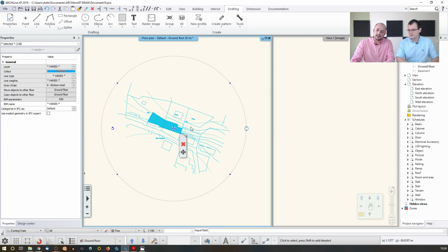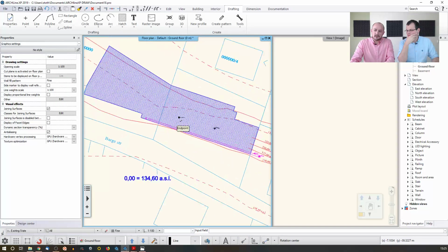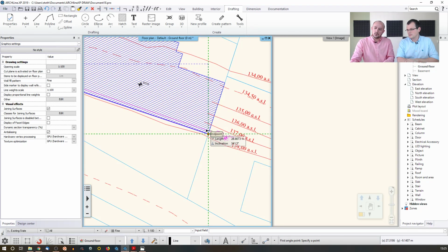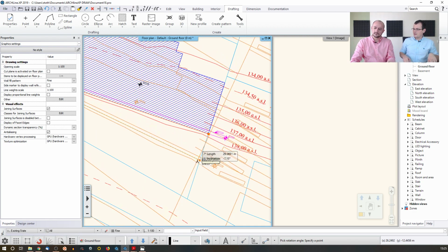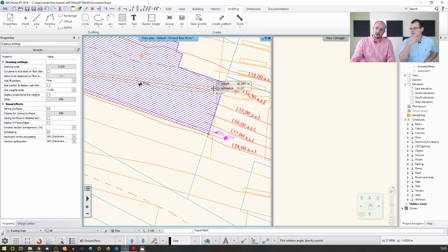So I click here, instead of the classic graphical rotation. So I have the rotation options, and now I can find the rotate from. This is a very handy tool because this allows you to set up a rotation origin. This is where I would like to rotate this whole content around. And then I can click and pick up a point, so one point, the rotation origin, stays where it is, it's pinned down, and the other one moves around it. Yeah, see, this is what happens.